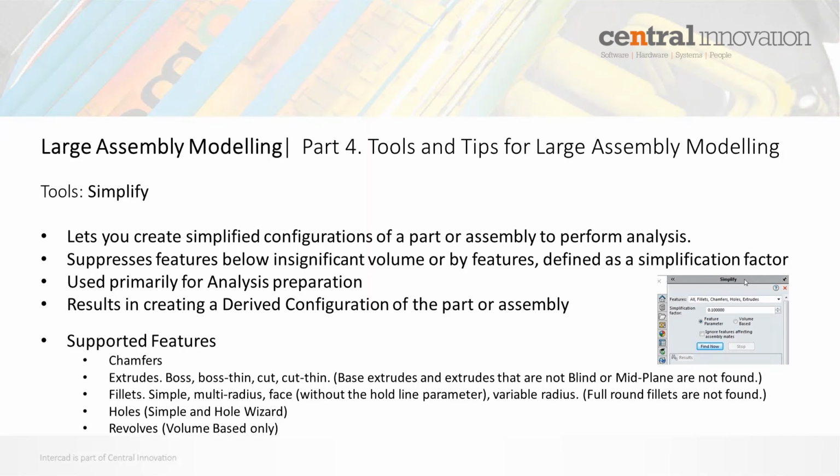The result is a derived configuration of the part or assembly, and the supported features here are chamfers, extrudes, fillets, and then depending on whether you select the simple and hole wizard options, holes, or if it's volume based, then it's revolves.